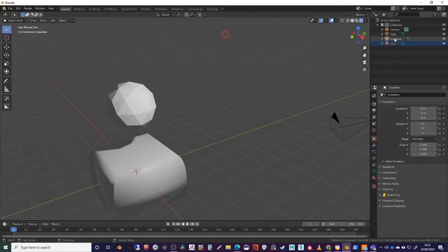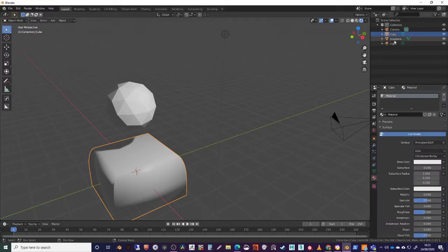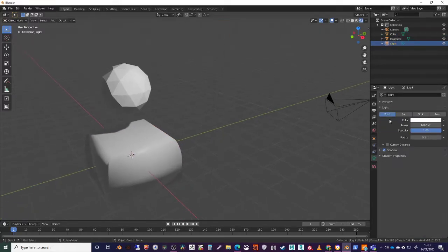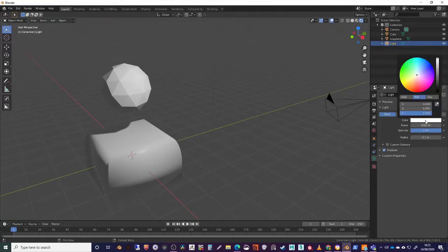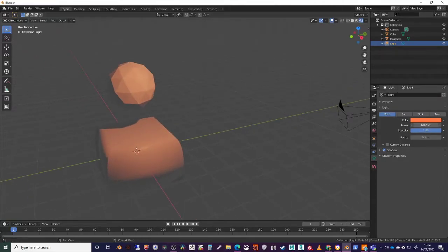It can be annoying sometimes, but it means you can bring up other properties at times as well, so you can switch around a bit. So this one is now selecting them. So we're now into the cube mode for the parameters. We can go into shading mode or the light mode. If we go up here, we can change the color. We could change the power, the wattage of the power. So let's put it at 2200.